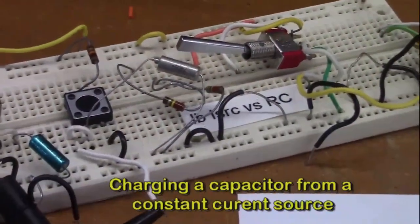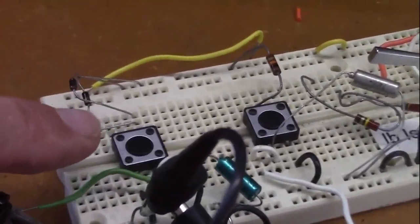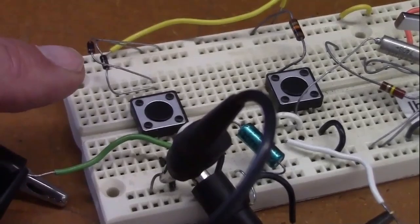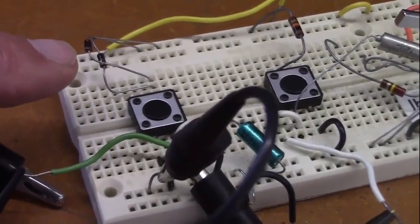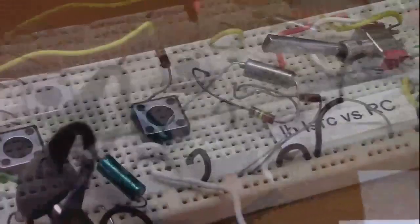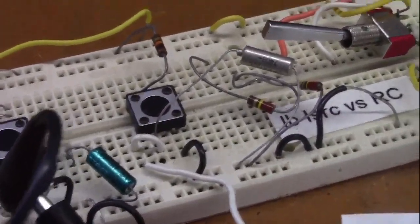So what we have is a current source. These are special diodes that allow a constant current through. Each one is 0.75 milliamps. We have two of them, so we have a 1.5 milliamp current source. And we have a capacitor. The capacitor is connected to the current source and ground.